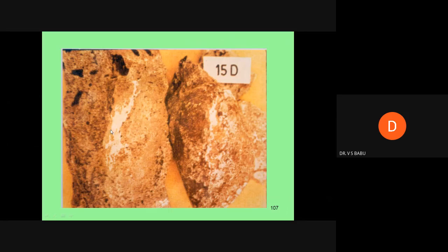Okay, now you see these white color patches. This is nothing but your ASR problem. But luckily in India, we have granite stones. All the parent stone sources are granite sources. So granite rock is generally not attacked by the alkalis. So we don't have that much problem with the alkalis. Only cold countries, some other countries, have ASR problems much.